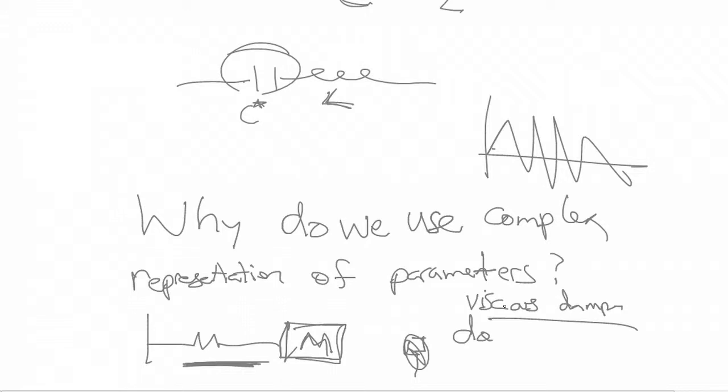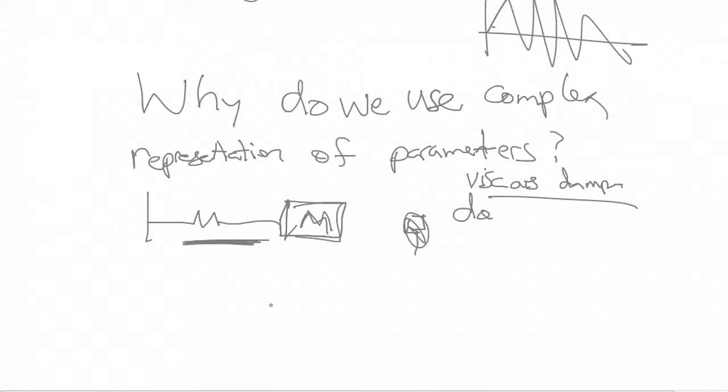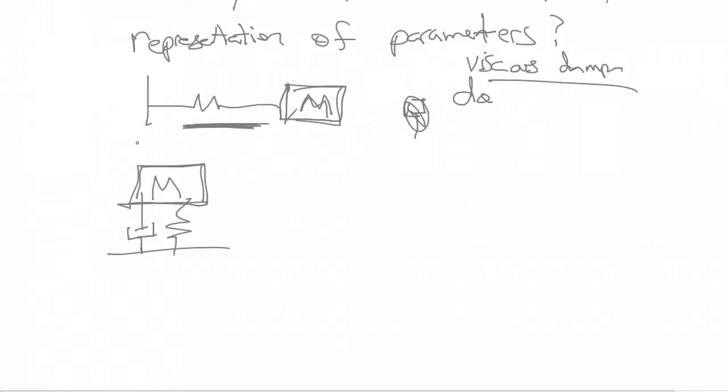Viscous fluids show this damper quality quite well: the faster you pull on it, the more it pulls back at you. So it's very good for liquids, and maybe a hydraulic system, it's great. But for a piezoelectric material system, where the lost energy is proportional to the stored energy, you definitely don't want to use a mass spring damper. You want to use complex.